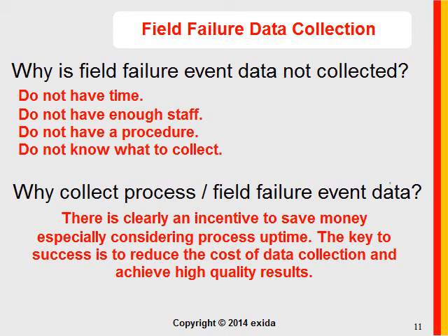So, I visited a refinery a couple of years ago, and they had an excellent database of evaluated process relief valves. And the reason they had that, it was a requirement by ASME that every 3 years the relief valves were pop tested.